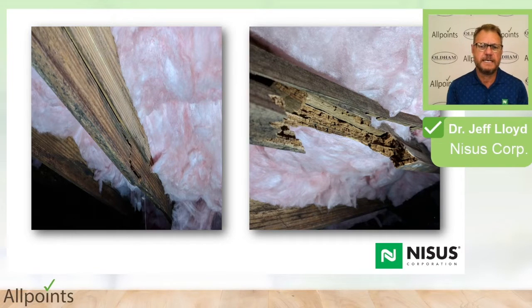If the moisture content gets a little bit higher, then we start to see not only mold growth but fungal decay. And this was a crawl space in a home that I went into that had a spongy floor. As part of a home inspection, you could bounce on the floor, and so I went into the crawl space, which I was going to do anyway, of course, to look at why they had a bouncy floor. And all of the floor joists were broken, and the reason they were broken is they all had fungal decay.